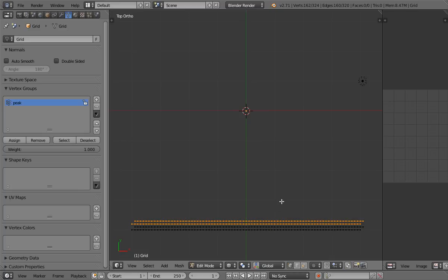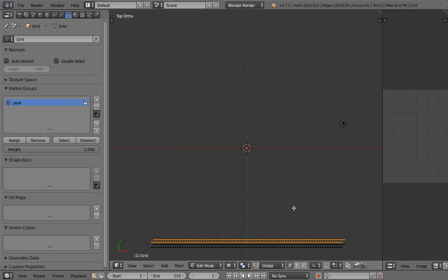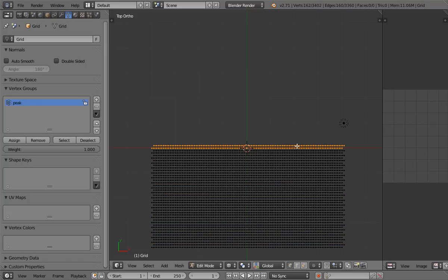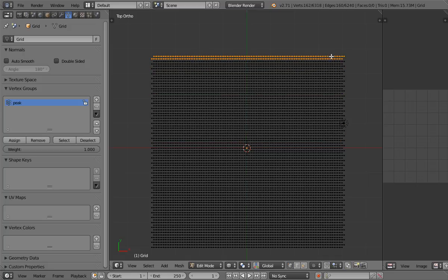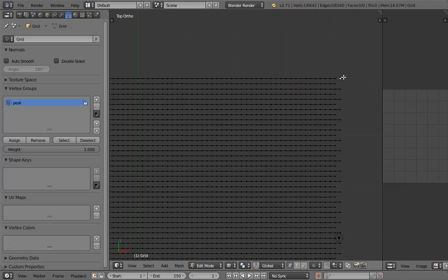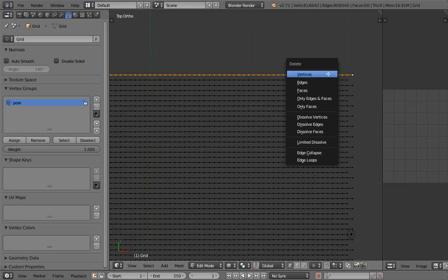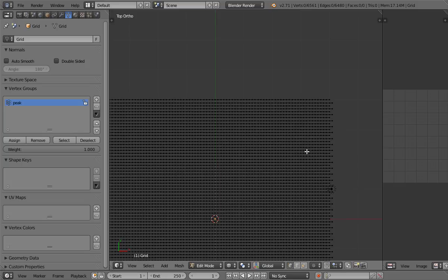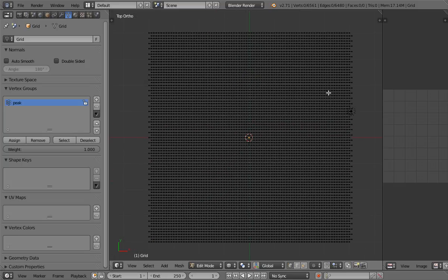And now we can automate this process all the way up by simply pressing Shift and R, which repeats the last action that we made. So press Shift and R and just keep pressing that until we get up to right there, which is 4 blender units above the x-axis. Looks like we created one extra line up there. So I'm going to select that by pressing L over that vertex and then press X to delete it. So here are our horizontal guidelines for the metal mesh on top of the microphone.